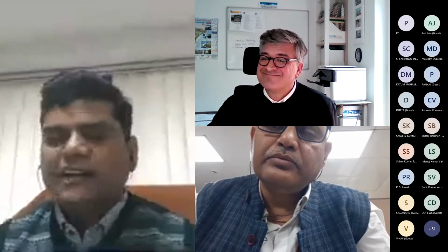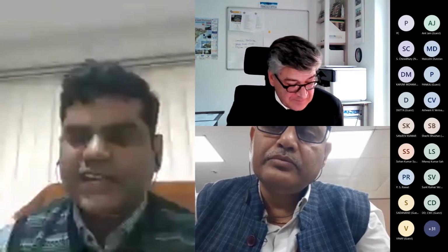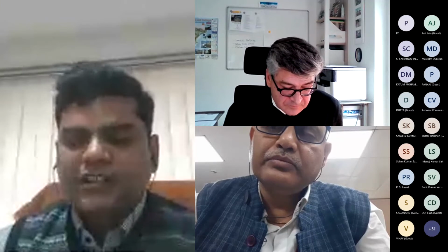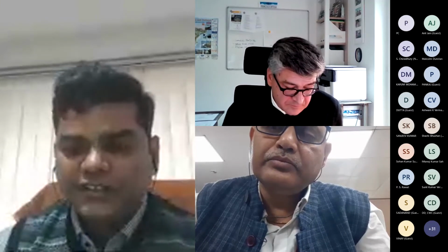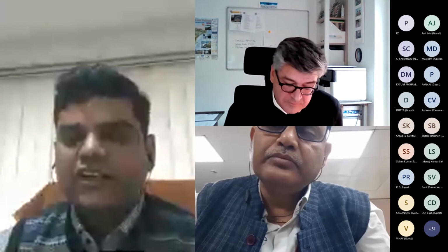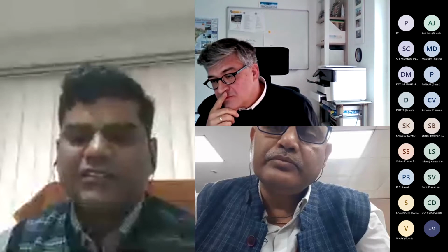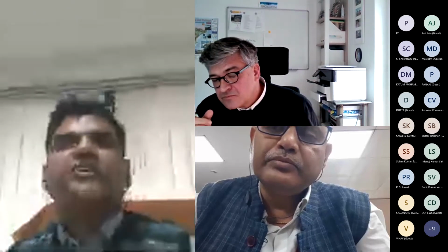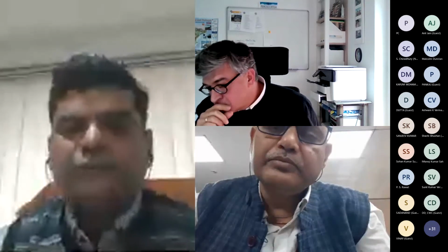One more question. In one of the slides, you said that you are reducing the aggregate size from 90 mm to 50 mm. While doing so, actually, we will be getting more heat of hydration. So how will you tackle that, particularly in India, where in summers temperatures are more than 40 to 50 degrees Celsius? In Fahrenheit, you can say 104 or more than that.